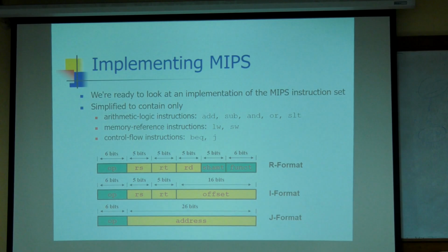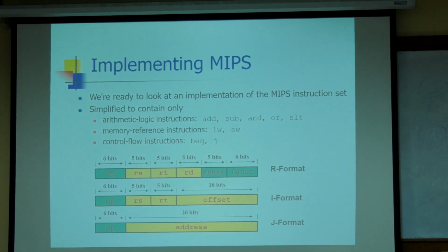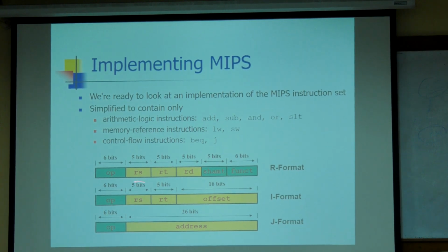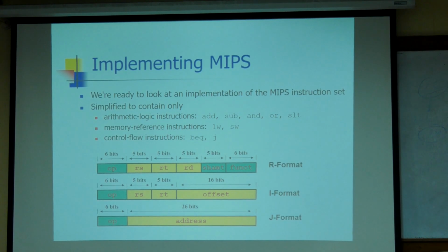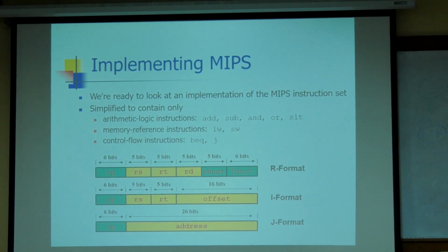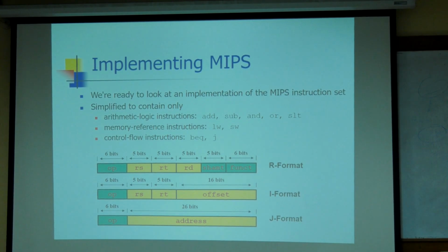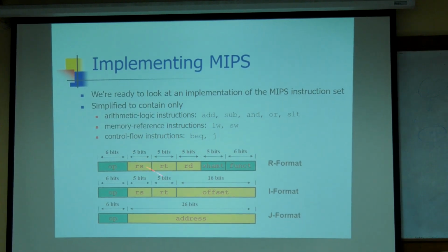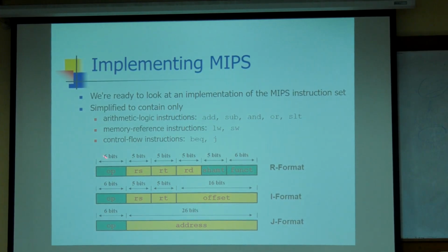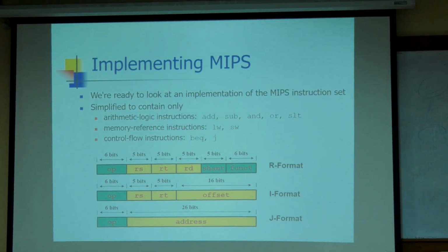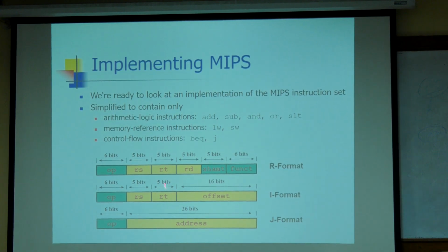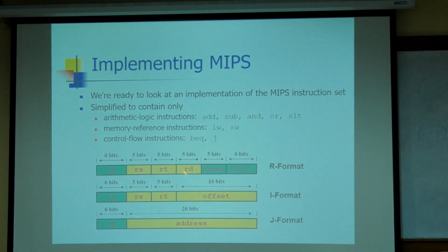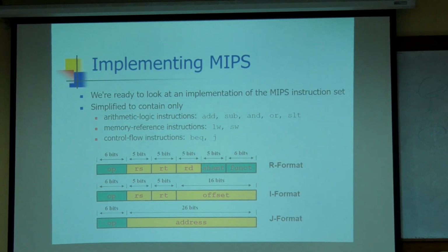So for that, there is a 5-bit address of that register: RS, RT, RD, source, target, destination. These 5 bits will indicate the address of the 32 registers present in the architecture. Out of those 32 registers, R0 to R31, which register are we using as RS? That 5-bit binary number we are going to enter there. Each register has a unique address. Similarly, the RT register address you have to enter here, those 5 bits, and these 5 bits will indicate the RD destination register address.